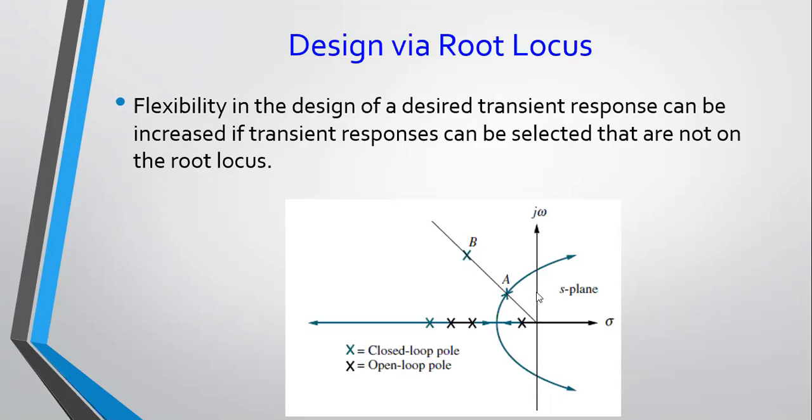We look at equations for how to define these two parameters, and once you set your damping ratio, we know we are also setting our percentage overshoot. So these three parameters, your percentage overshoot, your peak time, and your settling time, are actually transient response specifications. If you want a certain value, you can very well decide a gain on the root locus.